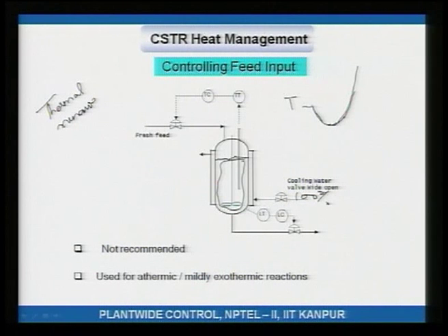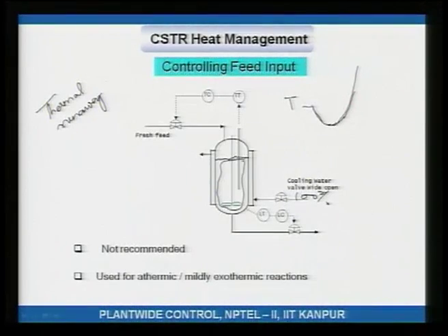what is happening is, when the temperature was down, you allowed burnable material or fuel to accumulate. Then, once the temperature starts to rise, this unreacted fuel sitting inside the reactor can catch fire, so to speak. What I mean by catch fire is, the reaction temperature will just shoot off and you can have a runaway. So, this scheme is susceptible to thermal runaway. Therefore, it is not recommended.